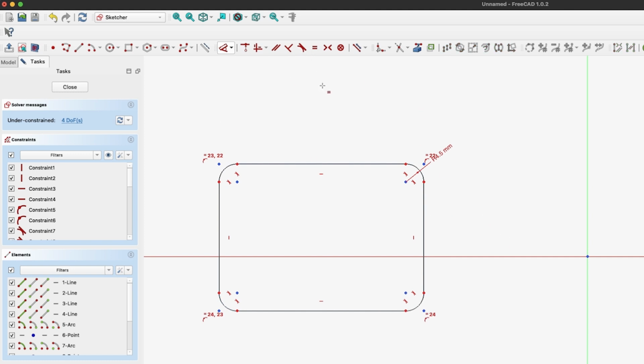Now before we go further, let me also tell you a very important condition or prerequisite for creating a fillet, and I would say this is also applicable to chamfer. If you want to apply a fillet, both those line segments, or even sometimes a hybrid, which I'm going to explain in our next example, should have an intersection point. They shouldn't be parallel to each other, because if two line segments are parallel and never intersect with each other, then it's impossible to add a fillet to them.